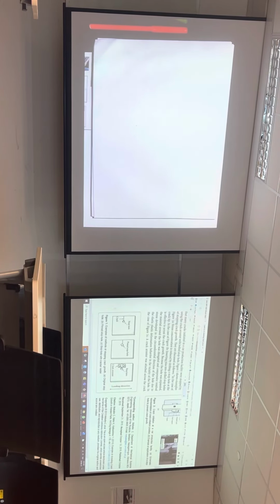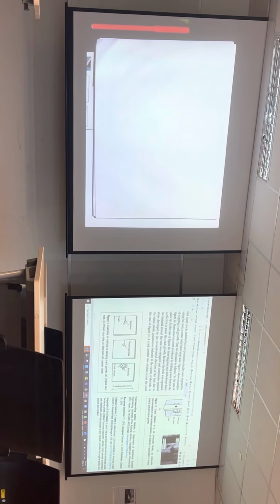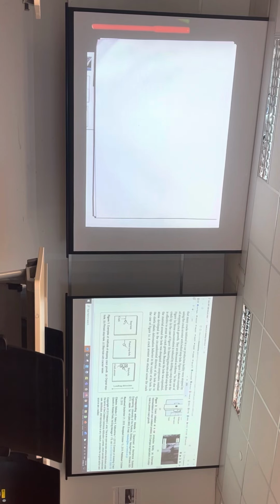So over here, drilling holes. You don't drill holes along the crack, but you have to drill right at the head of the crack. And hopefully after going through the class, you understand, without reading all the documents, what this bunch of people are trying to do.